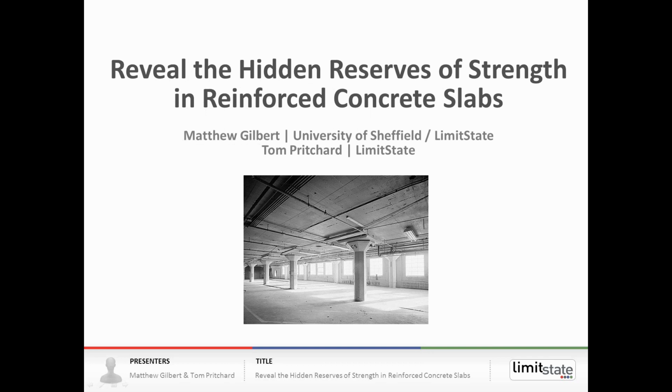We'll be talking to you a little about how you can use automated yield line analysis to analyse reinforced concrete slabs, often showing that they have more inherent strength than you might actually assume using other techniques. A few of the things that we're aiming to show you are how the yield line method has been automated, removing the uncertainty that you may have missed a critical pattern, and secondly how LimitState slab can be used to rapidly analyse a reinforced concrete slab, often demonstrating that additional capacity is present when compared to other methods. And lastly, a little bit more about the features of the software.